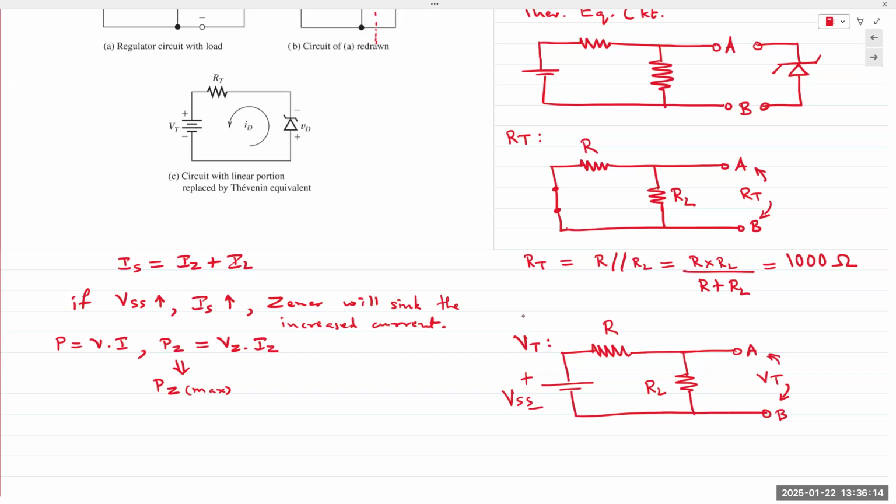If you're simply measuring the voltage, that means there is no component connected at that node. There's no component connected between R and RL. It means they are in series, indeed. And if they are in series and a voltage is being applied, what technique comes to mind? You can use Ohm's law, apply it twice, or shortcut voltage division.